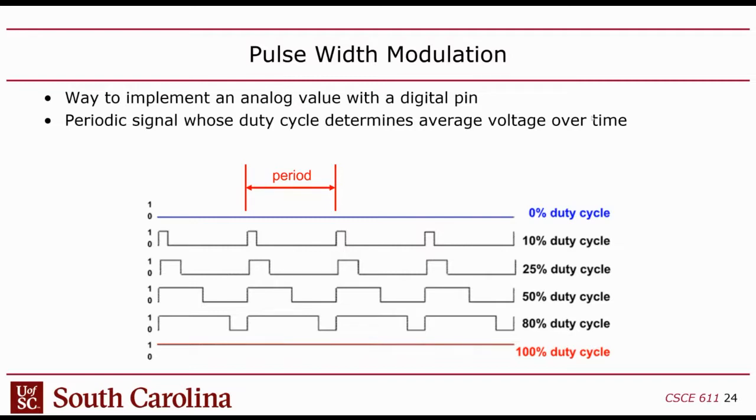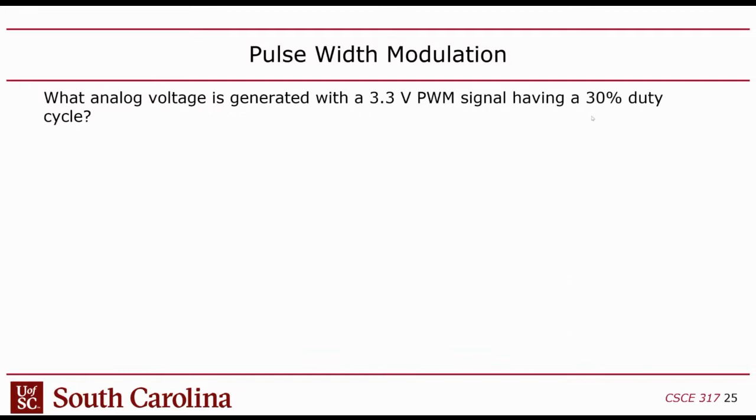So this is a quick one. Of course, you can't put a huge load on this either. With a motor, you may need an amplifier or something there too, because the digital pins aren't meant to drive a large load either. So there are a lot of restrictions here, but if those restrictions aren't a problem, that's pulse width modulation.